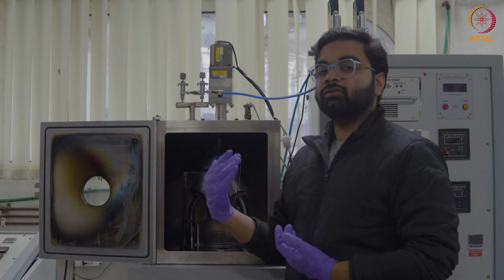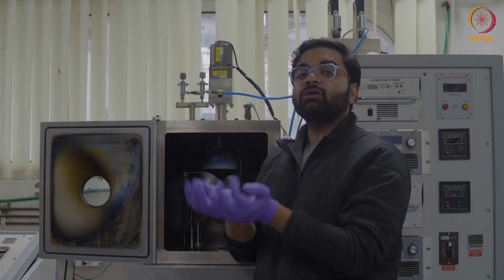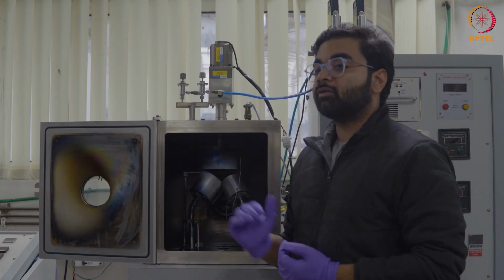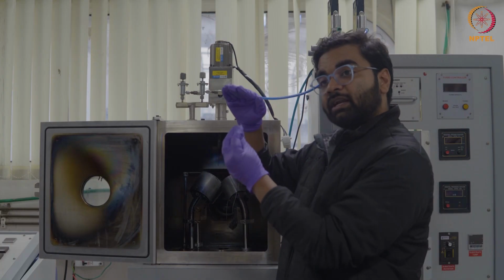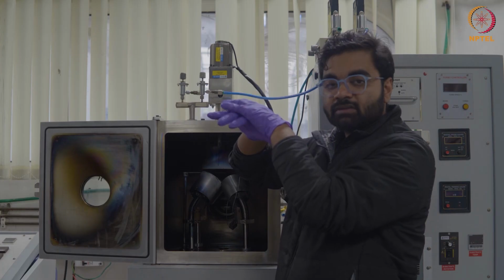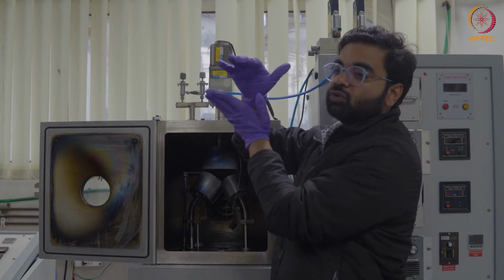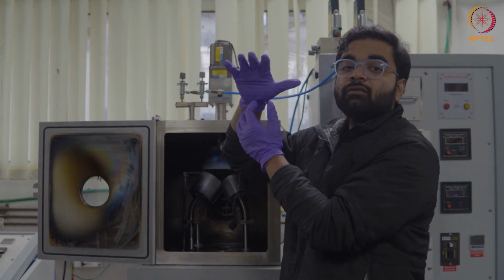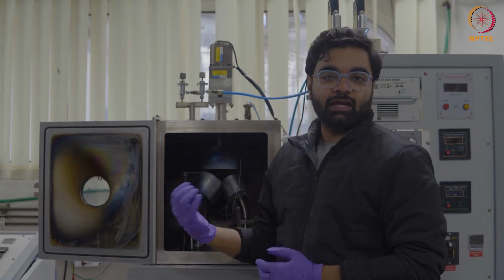It's very much controllable. If we compare it with the flash deposition technique, where the material just flashes off and gets deposited, the controllability is not there. Whereas in this case, you will get the good amount of controllability that you require. The second advantage is, since the material gets deposited atom by atom, the uniformity will be very good. Since you are also rotating the sample and giving substrate heating at the same time, the rotation and the substrate heating induce uniformity. And since it is atom by atom, the material will be very uniformly distributed, which means you can expect that uniformity to be maintained, which is not the case in flash deposition.